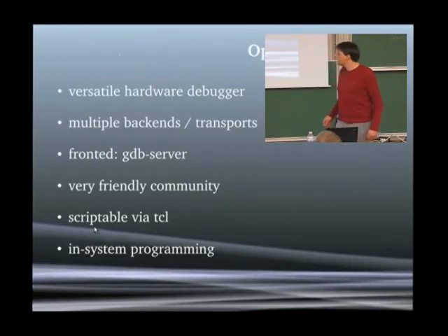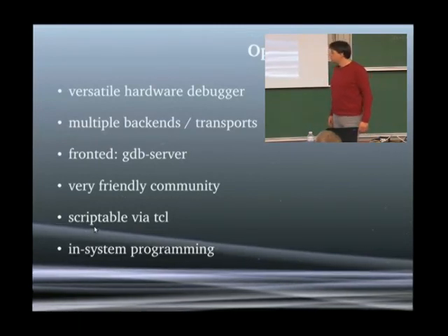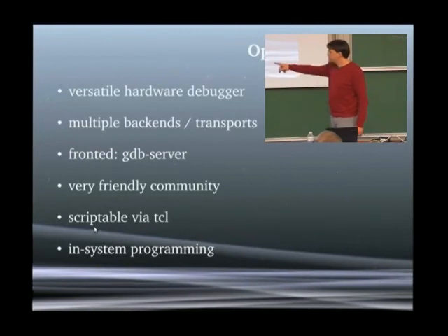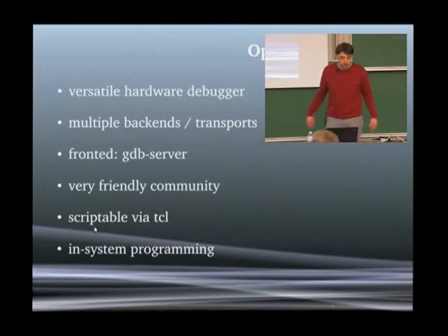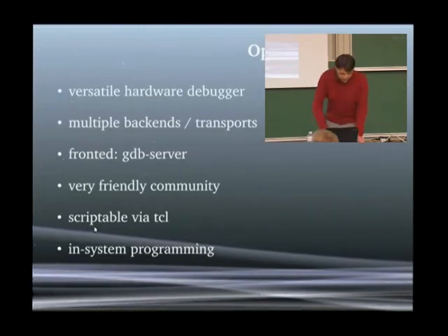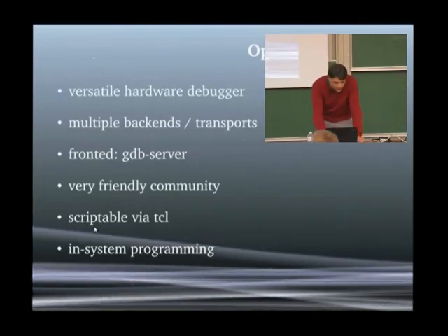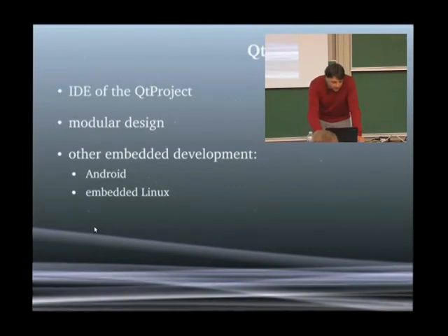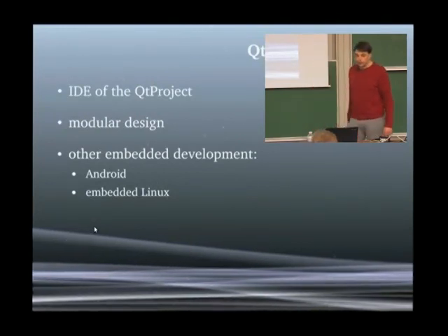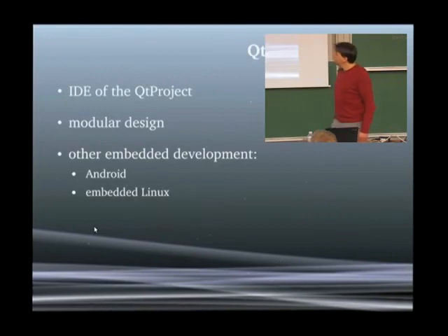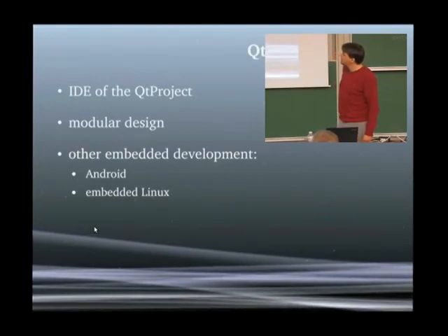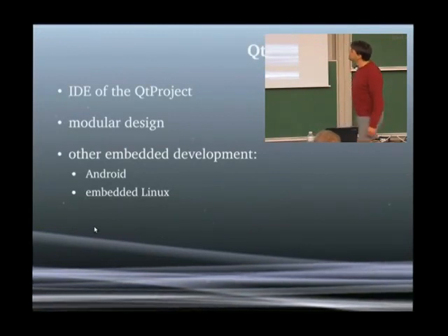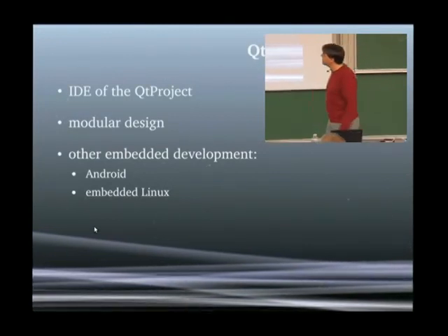This can be done via Tcl scripting. You can also use OpenOCD for in-system programming, but I'm not touching it any further, it's just for completeness. Yes, this GDB server is the backend for debugging, and the IDE is the QtCreator I'm talking about.